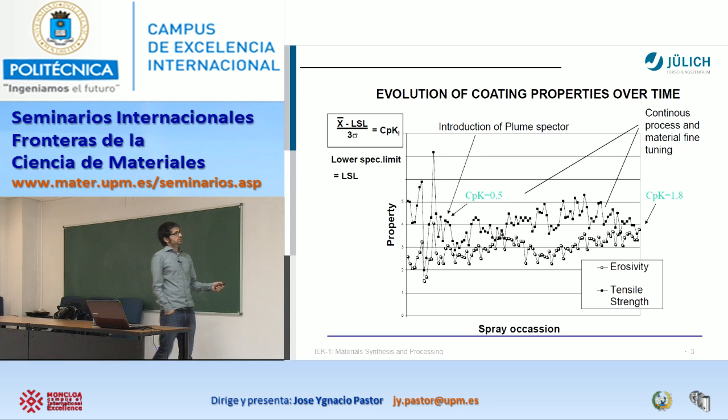But today it's about the properties, and I just want to show you a few examples, maybe properties like how it modifies over time, because here it is about the spray and how it works, how the stencil or the erosivity of the coating works. But something that I want you to have in mind is that thermal barrier coatings are for protection, but not like, okay, I want to protect for 10 hours or 20 hours. The idea is to work for several hours, okay? You cannot do a coating all the time to protect your metal substrates. It has to be there for a really long time and many thermal cycles, okay?